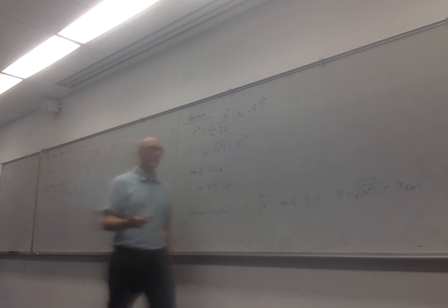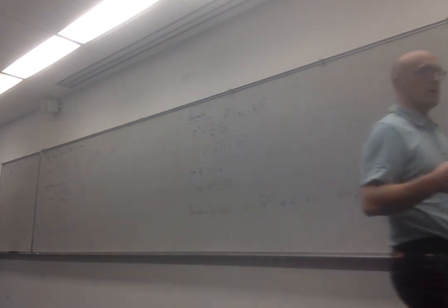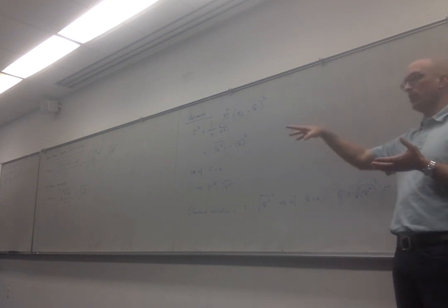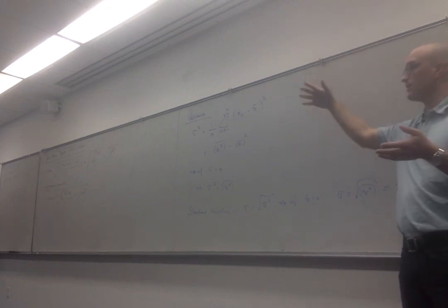In the simulation environment, those power density spectra that we'll see, and you're going to see later on again, are what they mean. If you go on the vibration table and select those things, that's where they come from. People take a complex signal. If you attach an accelerometer to a truck, you get a very complex signal.